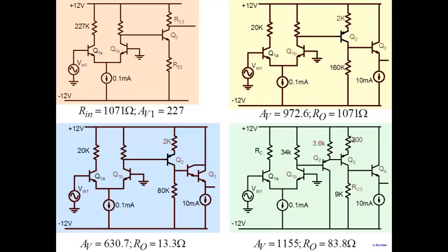And therefore, we can get a large gain as a ratio of these two, but use of a small resistor does not load the differential pair as well. So this use of a common collector stage allows us to reduce this particular resistor, therefore obtain a small output resistance, at the same time not load the previous stage, and we obtain a large gain also.